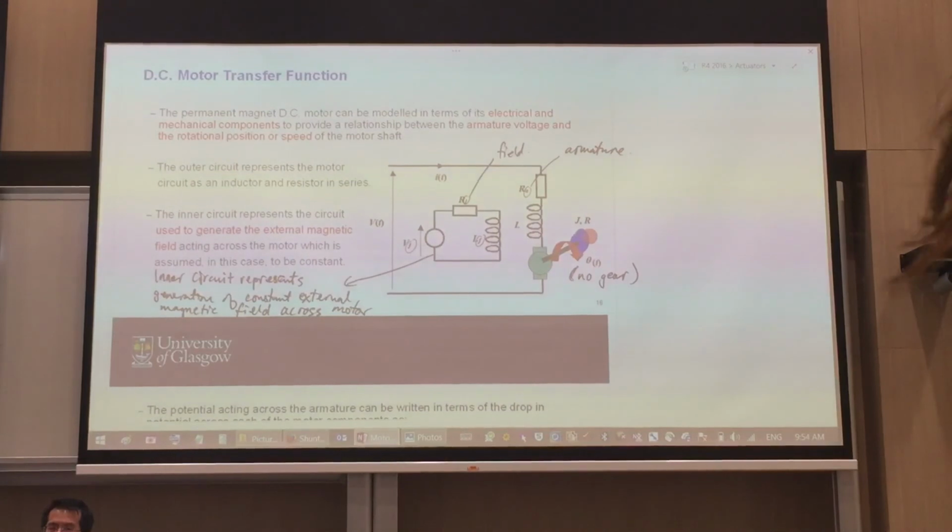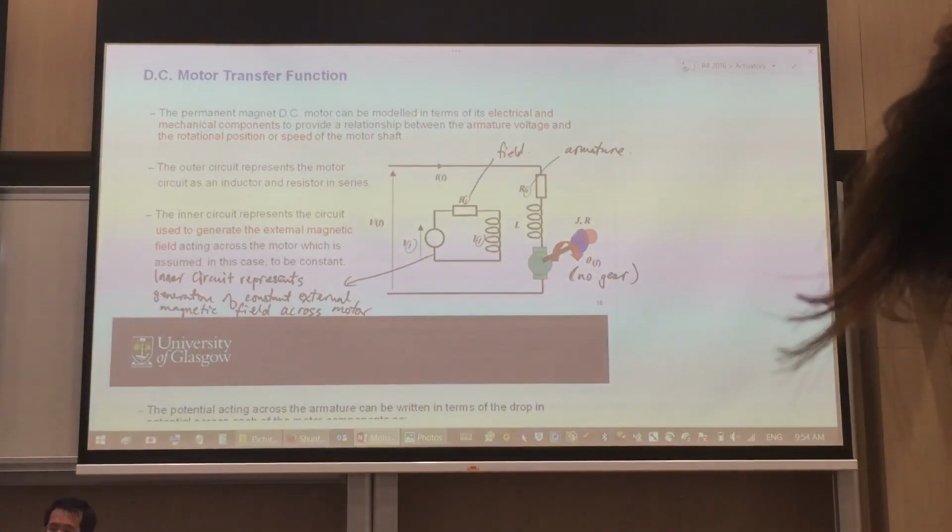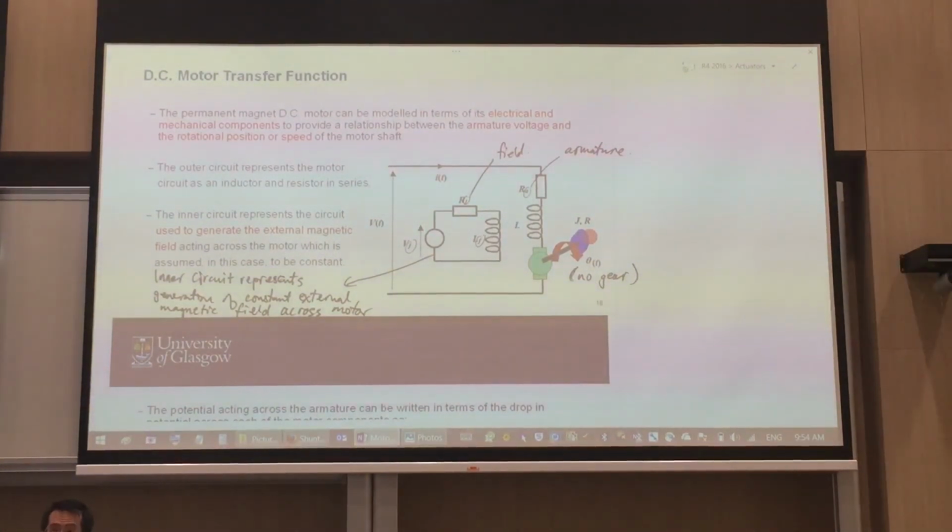Recently, there are a lot of washing machines or things that require a heavy duty motor to run. They sell it as a direct drive motor. A direct drive motor does not use gears. What it uses is this PWM signal, an on and off signal, in order to change the speed of this motor.